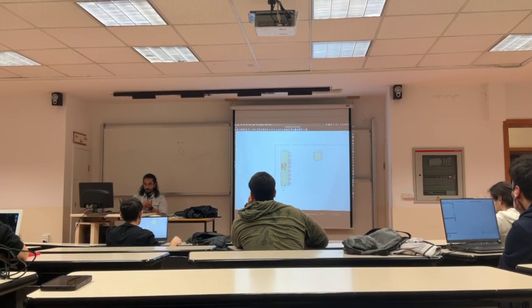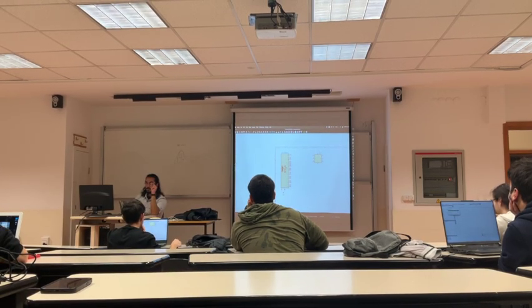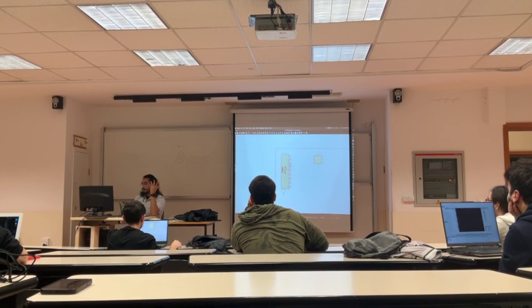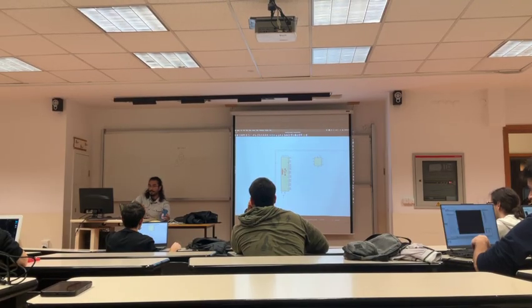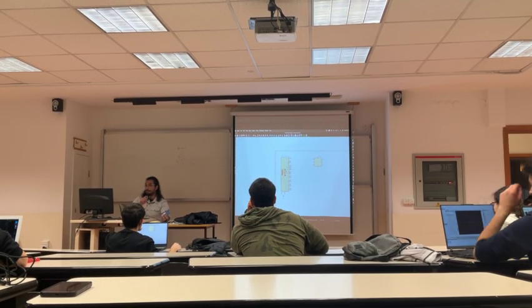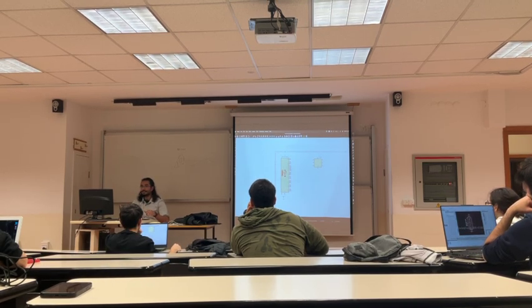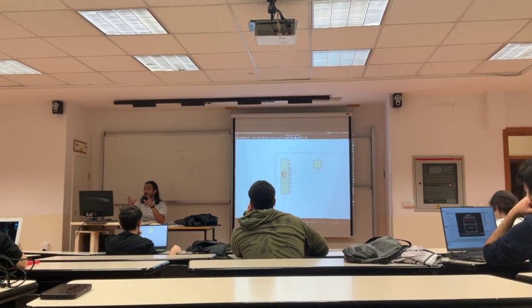I am going to now tell you how does USB Type-C determines which type of device you are. So this CC1 and CC2, if they are connected to ground, you are a sink. If these are connected to your VCC, which is the powering source, this is the powering device. So I want to charge my phone using my computer. My computer has these ports that are connected to the VCC, but my phone has the port that is connected to the ground. Okay, so it tells you these are not for powering it. These are for telling the other device, please send me electricity, I want it. Or telling the other device, I am going to send you electricity if you want it.